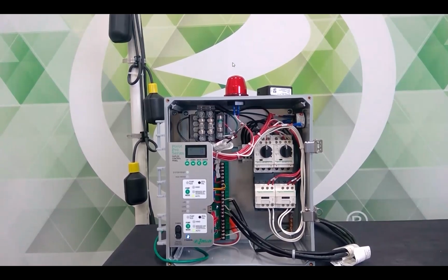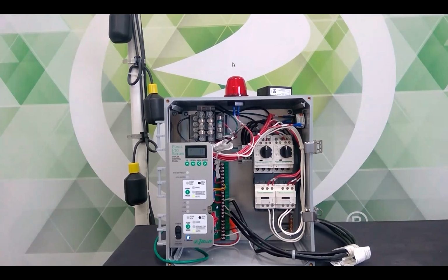By the way, alternating has always meant a ratio of 1-to-1. We thought, well, why does it have to be 1-to-1? If I have a duplex station for my house, I want any ratio except 1-to-1. And people are like, what are you talking about? Why is that? Because I want one pump to wear out well in advance of the other pump. I don't want to run the risk that in the same week that a pump fails, the other pump fails. So I'm going to do a 7-to-1 or a 20-to-1 or something like that.